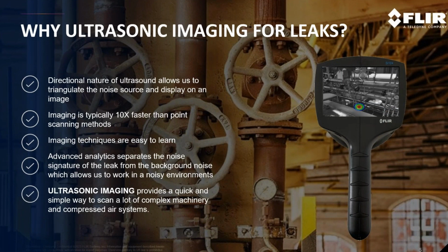So why are we using ultrasonic imaging for leak detection? Really, the directional nature of ultrasound, with our tool, allows you to triangulate the source of that noise and display it on the screen. As you can see here on the camera on the right-hand side, we see a small little corona, and that's an indication of where that leak is coming from. And those sounds are directional, so we're able to pick that up through our microphones on the front face of that camera. And we'll get into some of the specifics on the camera itself shortly.